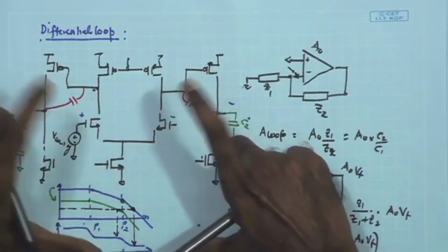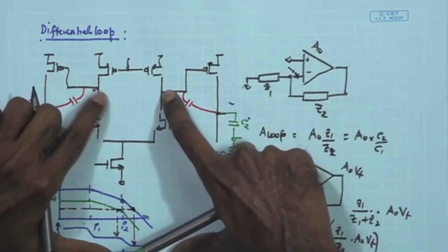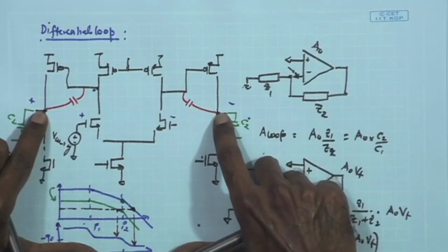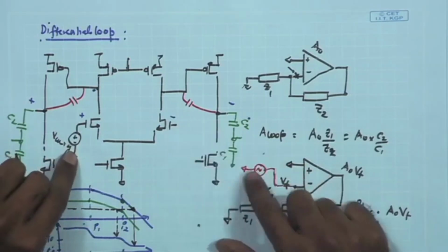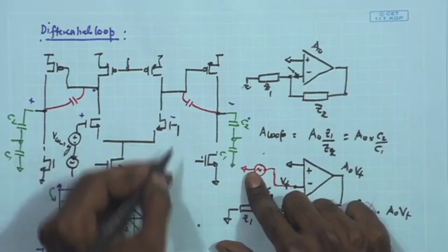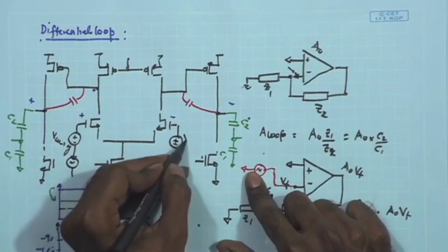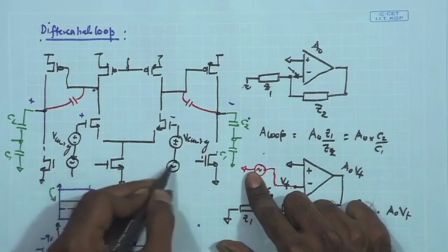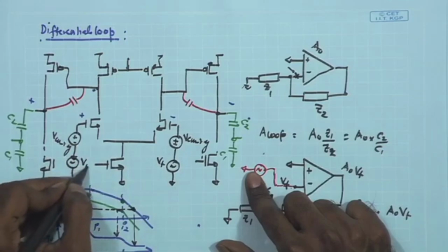Remember, in our circuit also we have used the resistive feedback to set the input common mode same as output common mode. So, in this case output common mode point was over here if you are using the same common mode feedback loop, and therefore, I am setting the input DC level equal to the VCM ref, and on the top of that you will be applying a differential signal Vt. Likewise, here I can apply the same potential VCM ref and apply a differential signal say minus Vt. So, you put this Vt and reverse of that minus Vt can be applied over here.